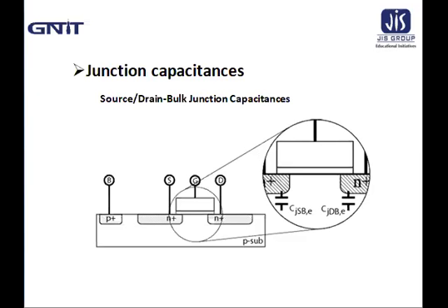Now, if we imagine the diode capacitance as a parallel plate capacitor, then because the plate spacing, that is the depletion region width, increases, the capacitance should decrease. So increasing the reverse bias voltage across the PN junction decreases the diode capacitance.